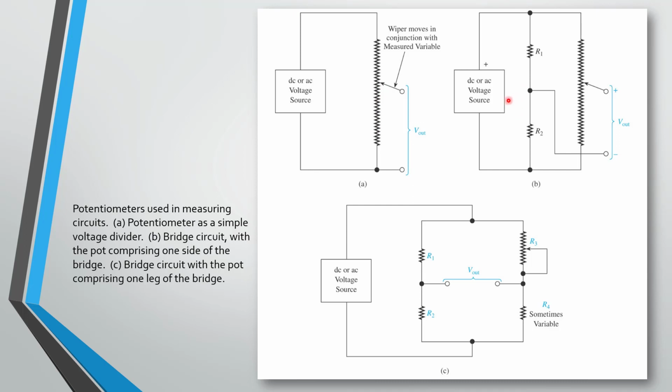In this case, what I'm looking at is a balanced situation, and I'm comparing a plus or minus. This is going from, say, 0 to whatever the max voltage is. So I'm looking at a 0 to some positive number. But here I can reference above or below a point. So I can actually convert this into a positive negative if I want to use this point as 0, because I've got this voltage divided in half by these two resistors. And I'm comparing that voltage, half of this voltage here, to whatever voltage I'm tapping into